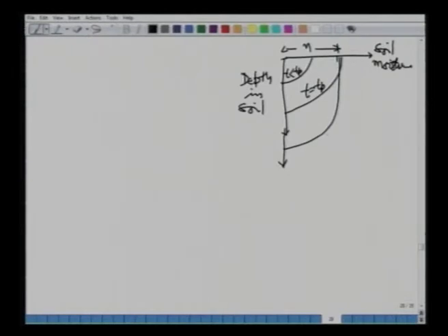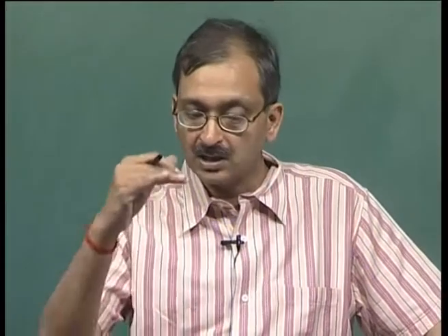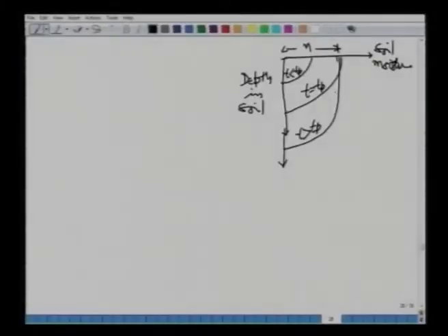And the third curve which you see here is for the time greater than Tp. After the ponding has occurred, what happens? The wetting front starts to move down, or the saturated zone starts to increase by a certain length. So, this one I can write is the saturation moisture content, which is equal to eta.